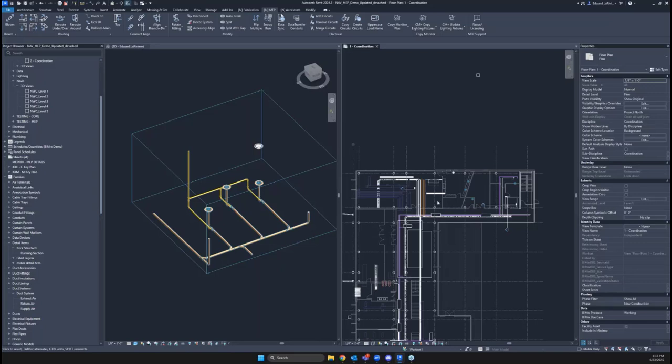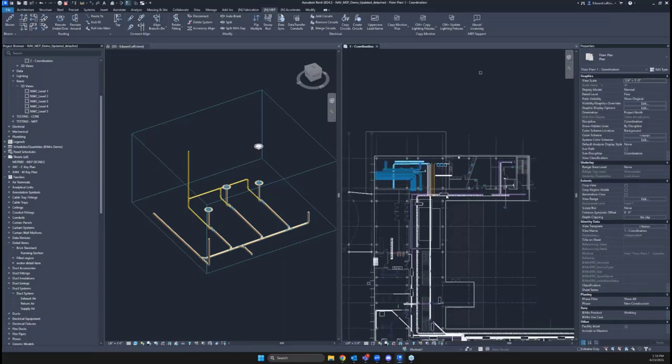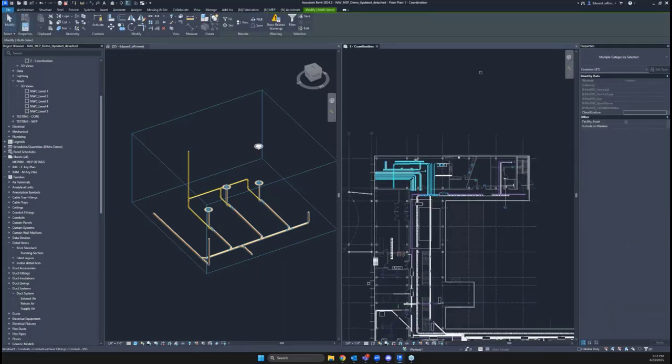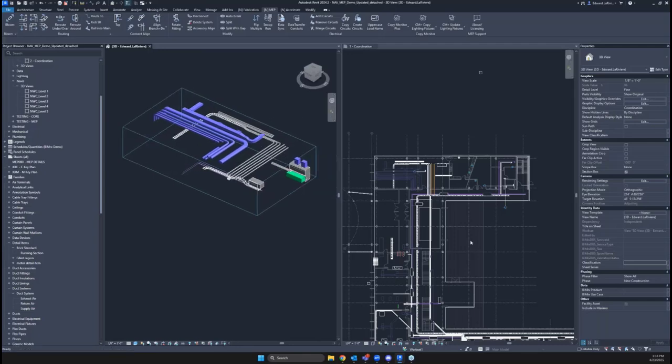So as we jump up into the ceiling and start trying some other tools out like Route 2 and Kick 90, and maybe these over-unders, I'd like to just remind you, yes, those do work for pipe as well, and they will work for ductwork too. All right, let's get to the ceiling. Again, that workflow of working in 3D is so nice, just grabbing the elements you want, 3D button, and now I'm working in a new area.